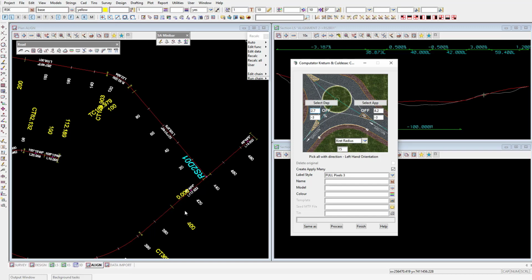Now this road here, if you've done the training with us, it's one-way crossfall, and the high side's on this side. So it's actually the approach that's positive 3% crossfall, and the departure, this road's just a simple crowned road, the road heading up that way.